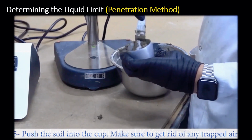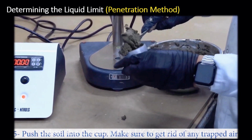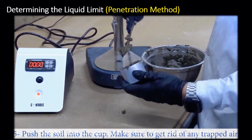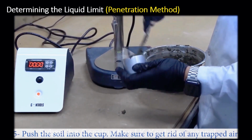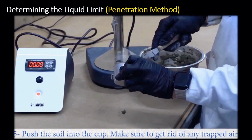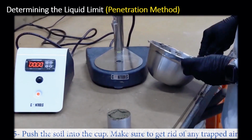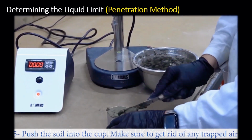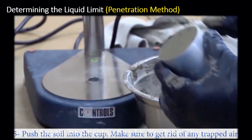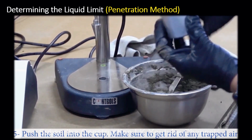We should make sure that no air is trapped in the sample. Then the soil should be leveled off at the rim of the cup to give a smooth surface.